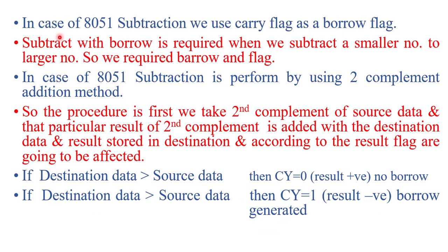Now some points to be remembered in case of subtraction operation. In case of 8051 subtraction, we use the carry flag as a borrow flag. There is no borrow flag in 8051, so for borrow we use the carry flag. Next, subtract with borrow is required only when we subtract a larger number from a smaller number, so we require the borrow flag. And in both cases, with borrow or without borrow, the syntax is the same.